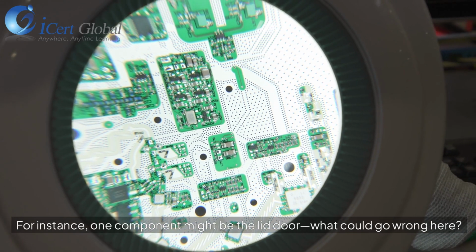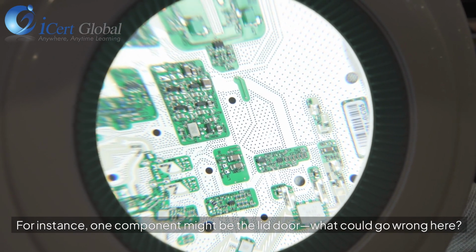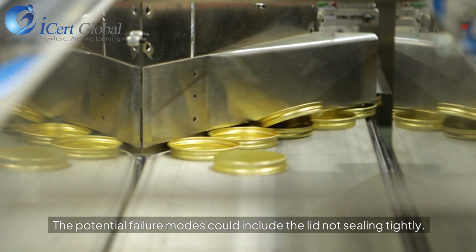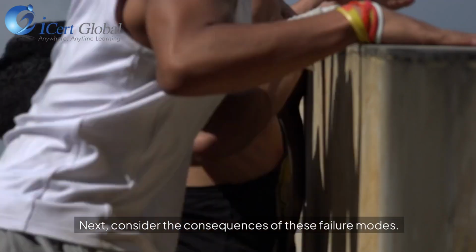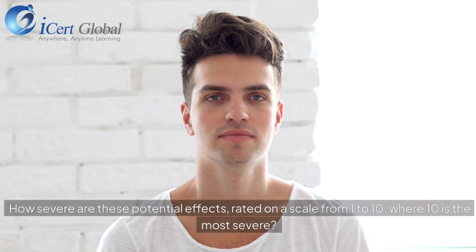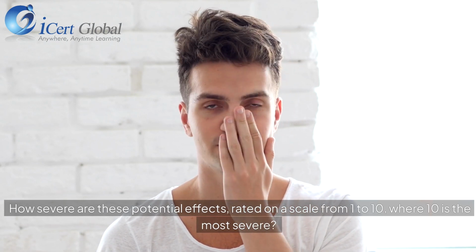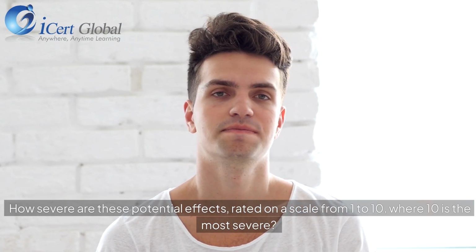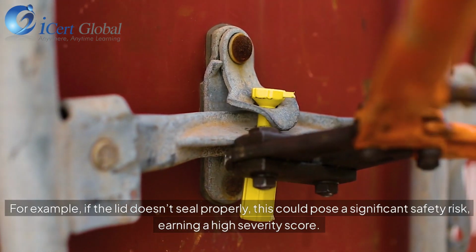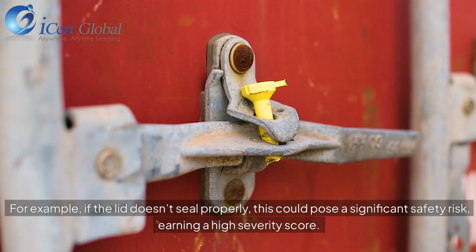For instance, one component might be the lid door. What could go wrong here? The potential failure modes could include the lid not sealing tightly. Next, consider the consequences of these failure modes. How severe are these potential effects, rated on a scale from 1 to 10, where 10 is the most severe? For example, if the lid doesn't seal properly, this could pose a significant safety risk, earning a high severity score.